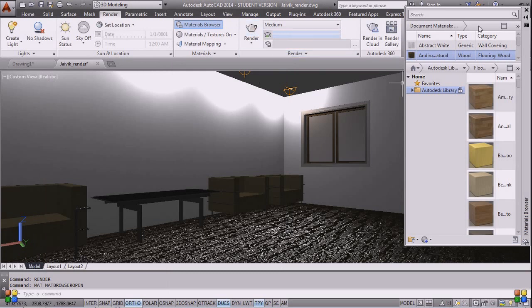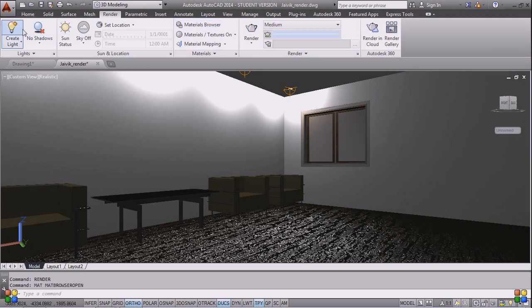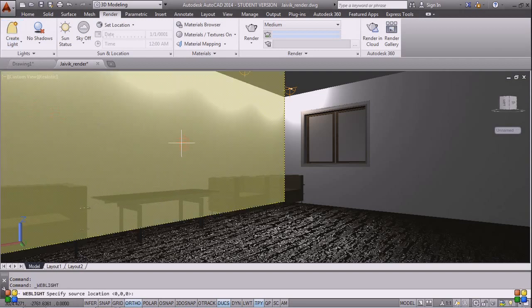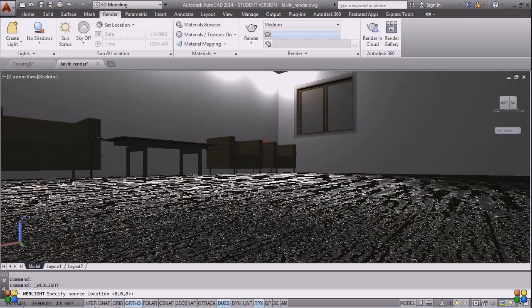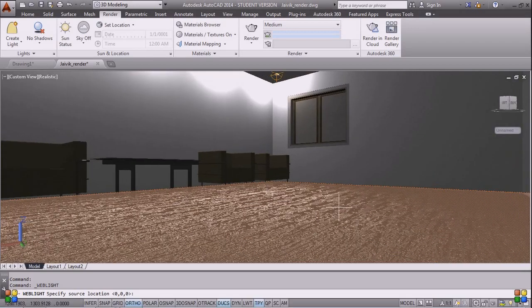So for that I am applying here a web light to solve the problem of darkness. I want to apply it in the center of my room, so I am giving here the M2P command for mid between 2 points.